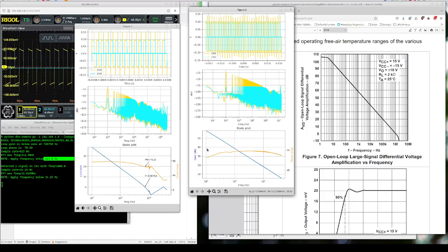But well, here at 1 kilohertz, I see that loop gain is, well, can I round it? I think about 60. So at 1 kilohertz, it should be 60. And I think that, yeah, that is what this also tells. So this entire plot all the way, but you do see I now miss something here. So there is 100 kilohertz, 200, 300, 400 kilohertz. And that's also why I don't plot the phase margin, because I don't cross the 0 detection.